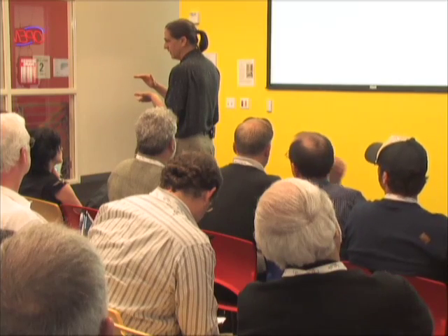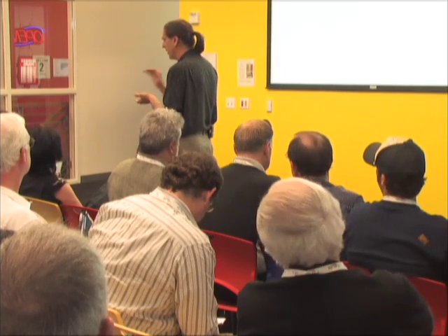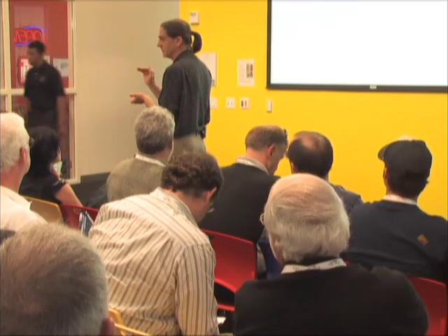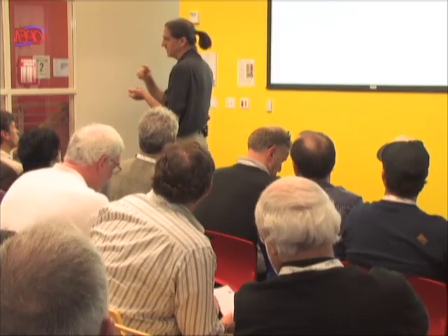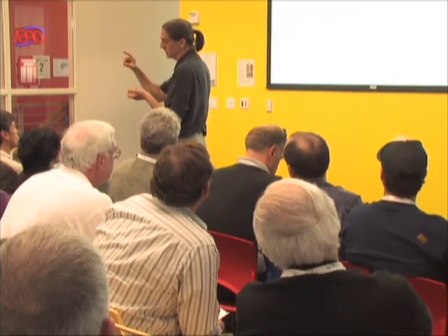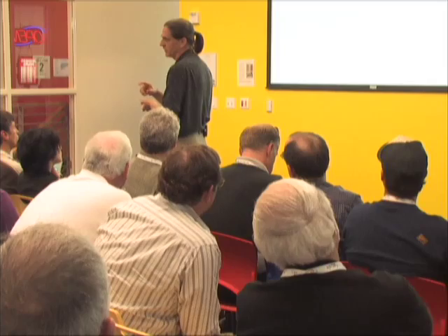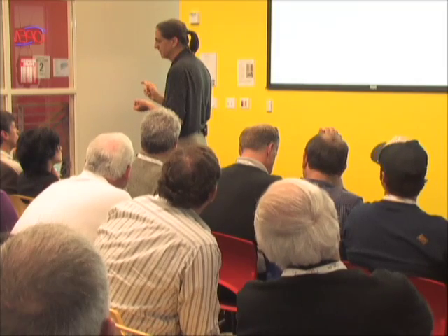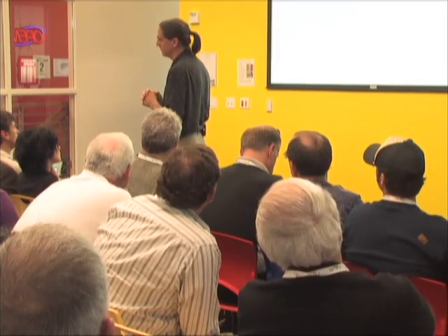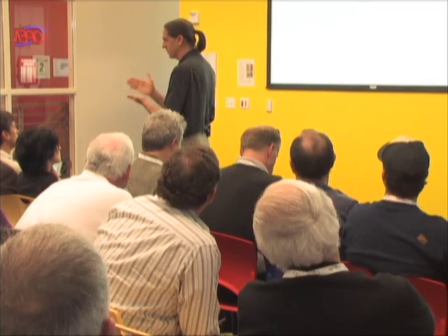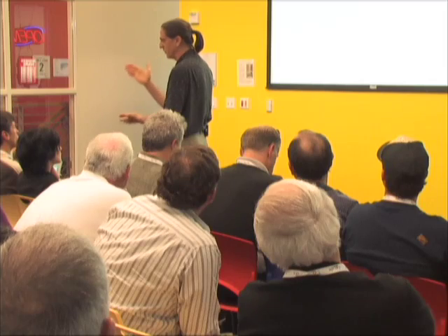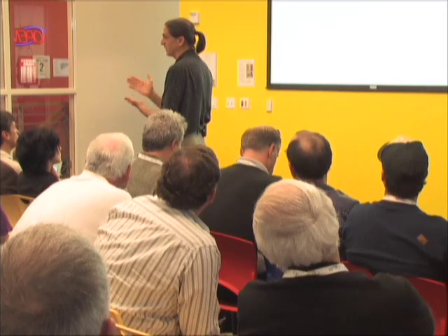So that it's checked to save the section. Yeah. And all I'm saving in that scene is sections. So if I have 20 sections, I'll create 20 scenes that have one section dedicated to each one, just so I can go back to them. So each scene only has that one section. Yeah. And we tend not to bury sections within components because they never turn on when you want them to. It's a really neat trick to be able to do that.